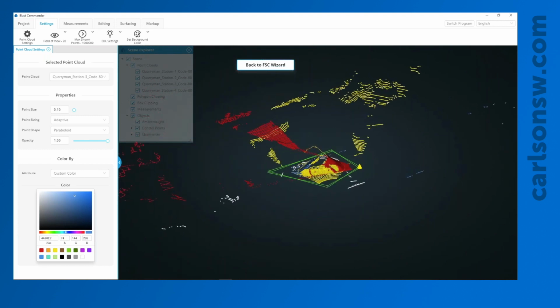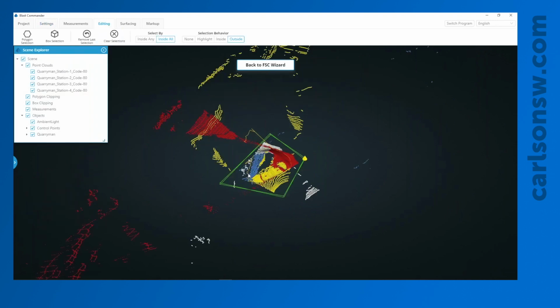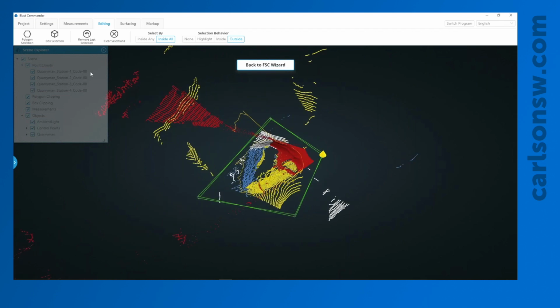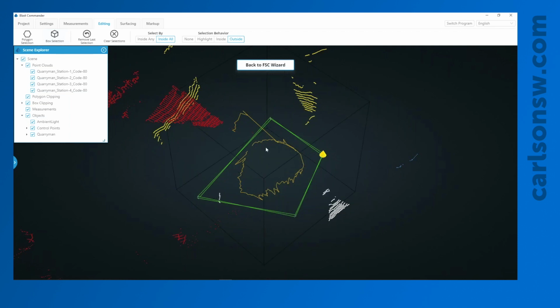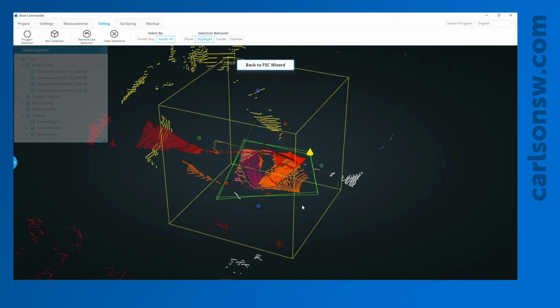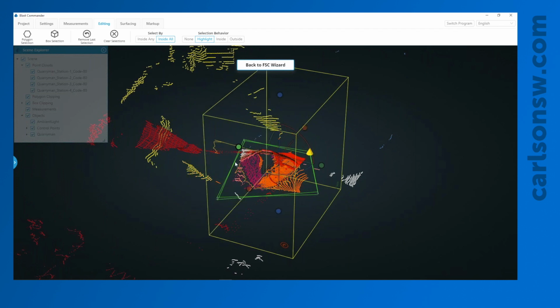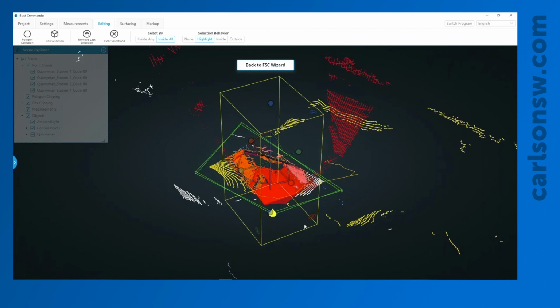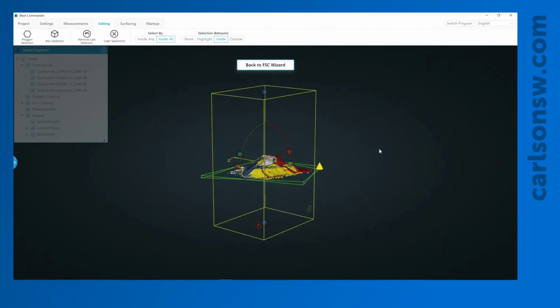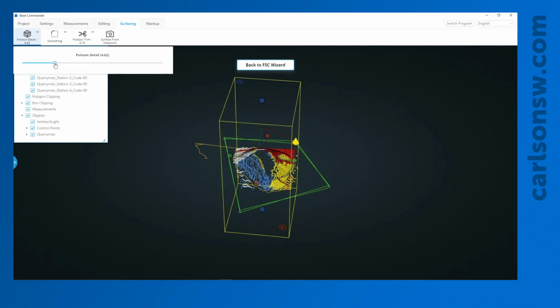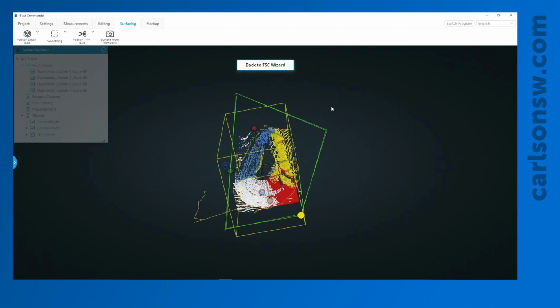And really from here, we would just go to our editing. Rather than take out all the points on the outside, since I just want to focus on the stockpile, I would use my box selection tool to finesse that. Maybe I'll go highlight at first, which with all the different colors is a little interesting, but we'll continue on here. And then we'll switch to inside. Surfacing. Maybe we won't have our detail all the way up at 14, we'll leave it at 8, and we'll look from, again, inside out